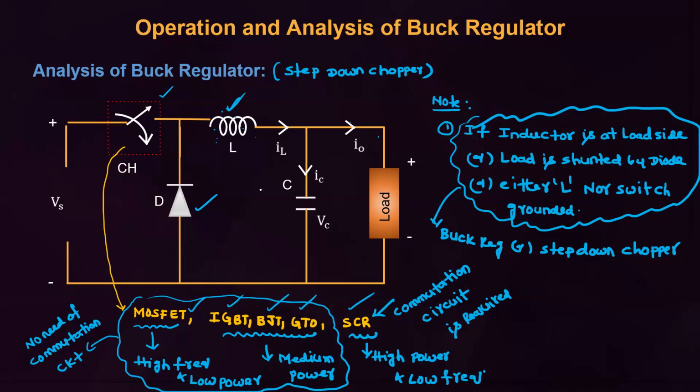And one more point to remember. Sir, what is the difference between the chopper and regulator? Either chopper or regulator, both analyses are the same, students. Even though they give the chopper or they give the regulator, the analysis is the same. But the only difference is a chopper with filter is a regulator, and a chopper without filters is the chopper. For example, the same circuit I will represent like this. This is the chopper, but if the circuit is represented along with L and C, then this is the regulator. If the regulator is given or chopper is given, same analysis.